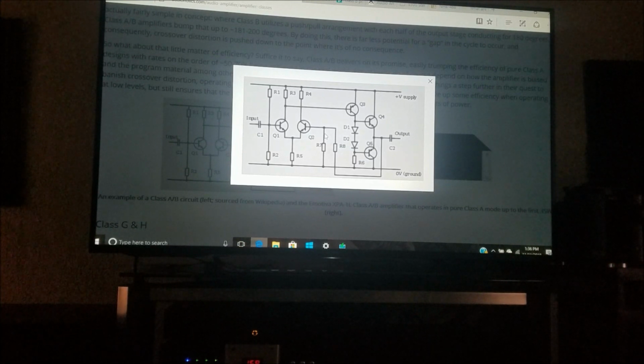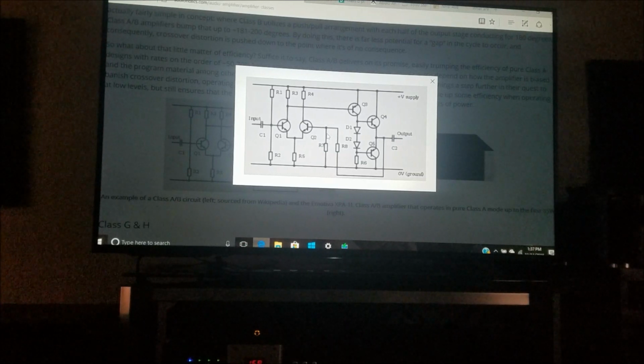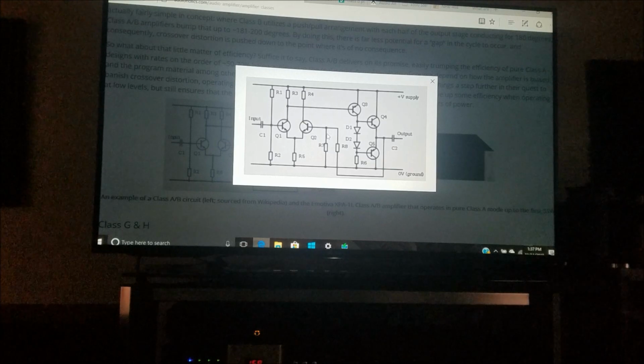And I was working a lot with BGA technology, or ball grid array soldering technology. But that's really when I ultimately found out that Class AB amps sacrifice efficiency over Class B amps in favor of linearity. And that's why they're less efficient, below 78% for full amplitude sine waves, at least in transistor amps, typically much less in AB vacuum tube amps.